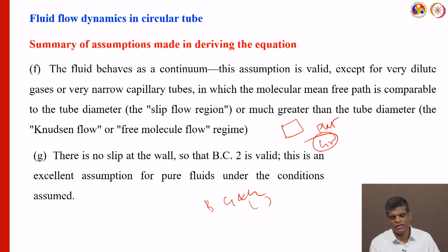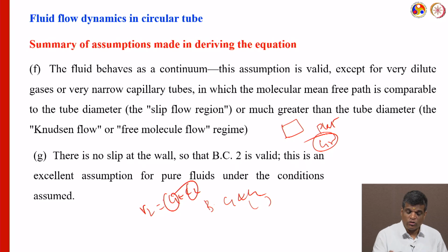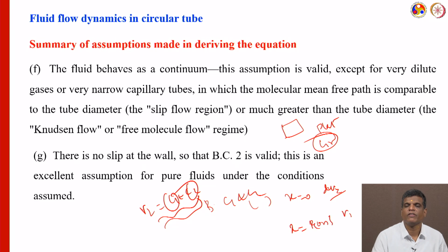If there are two constants, for example V equal to C1 plus C2, we cannot solve just like that. When you have two constants, you need two boundary conditions, then only we can solve it. At x equal to 0, what is the value of dVz by dx, and at x equal to r or delta, what is the Vz value. Like that we will discuss more on this.